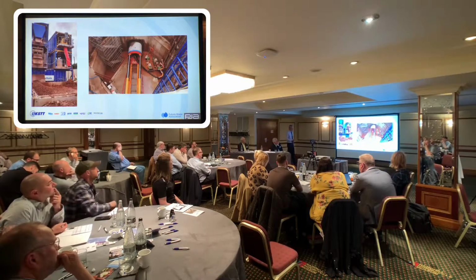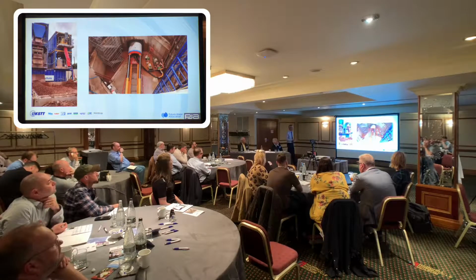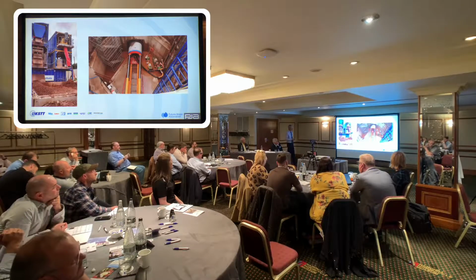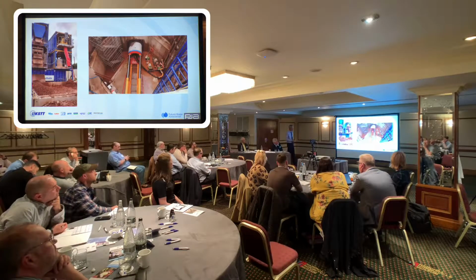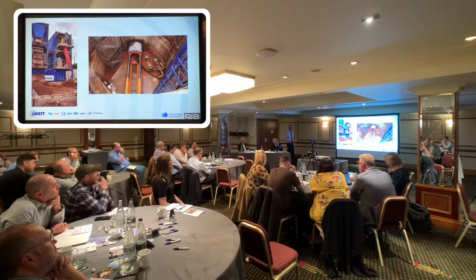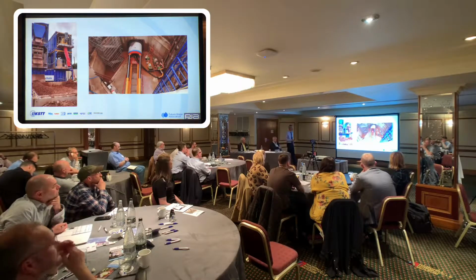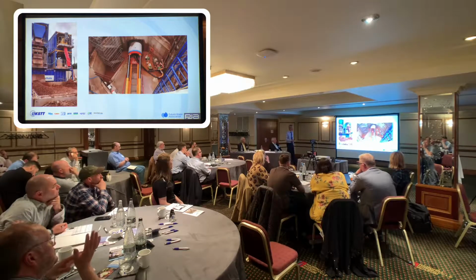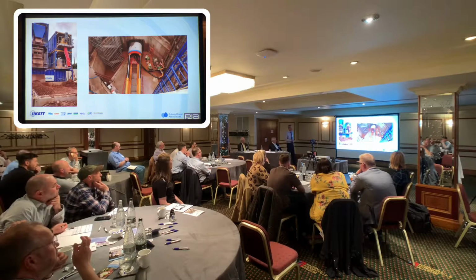So as I was saying, a key component of the feedback to the operator is being able to see the spoil, and this is spoil coming off the coarse screen, so you can see the granular material there, and this is the clay and silt that's being taken out by the centrifuge system. This pod here is where we mix the flocculants, so there's two barrels in there which are constantly filled with flocculant, and the flocculant comes out into the spoil. So we'd often bund these areas because there's quite a high water content, and you'd bump the water off the side.